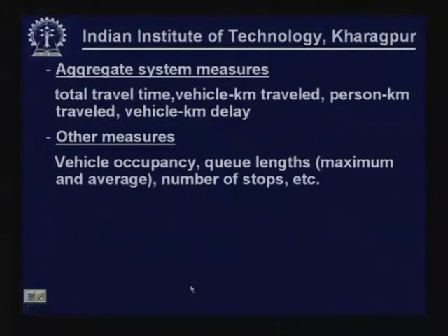So, instead of using only the volume, it is more rational and logical to use a measure like volume to capacity ratio. You know the relative loading, or the relative demand on that road as compared to the capacity, or to what extent the road system is loaded.